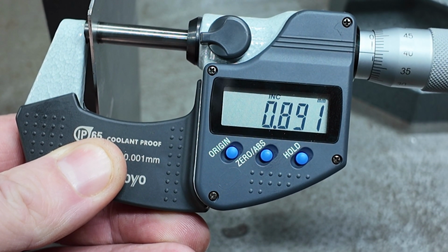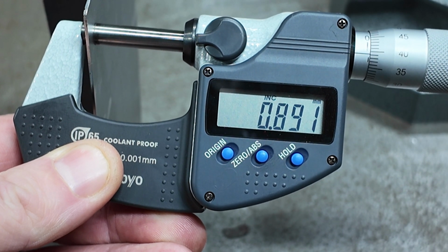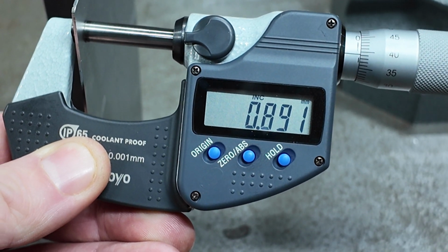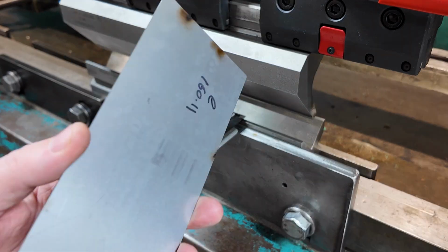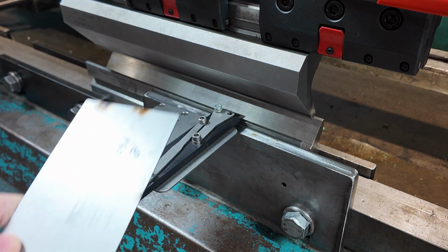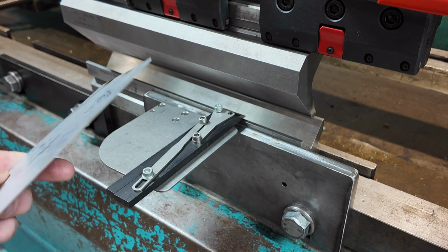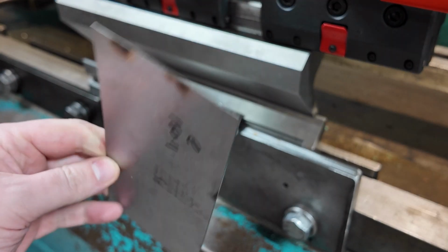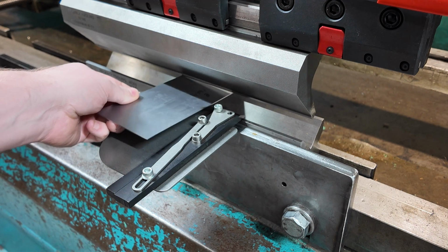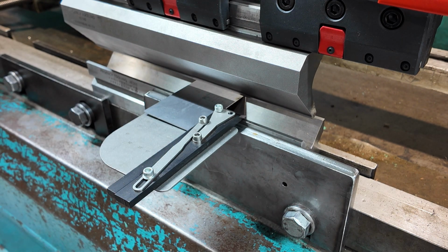So we're going to do a bend on this part, and for the purposes of this example we'll do it on the 50 millimeter V. We're going to bend the piece we've just measured. It doesn't matter where we bend it, because we're just going to add the two numbers together. All we're interested in is how much the material stretches or compresses around the bend. So get that on there, it's square, and let's bend.